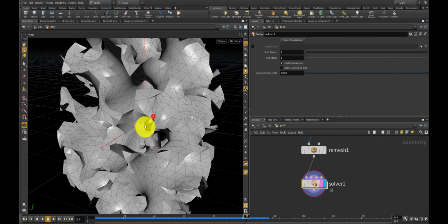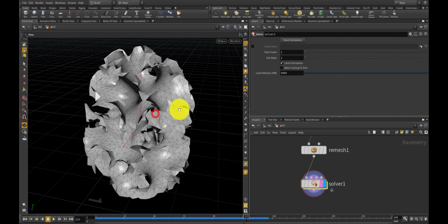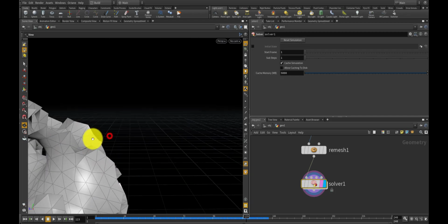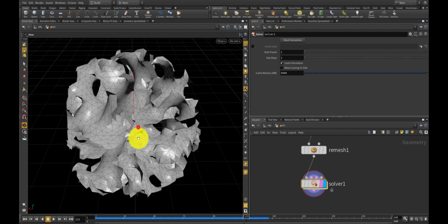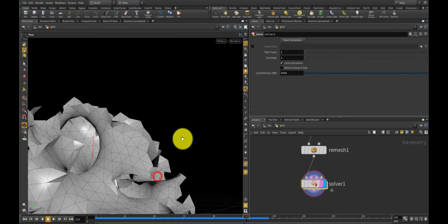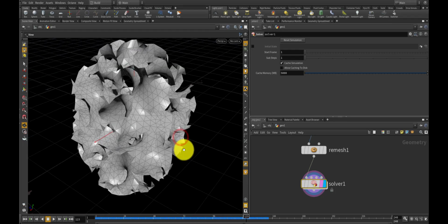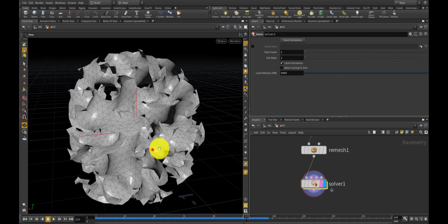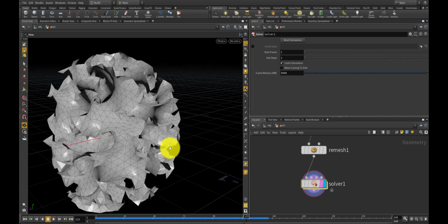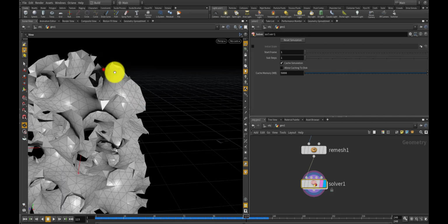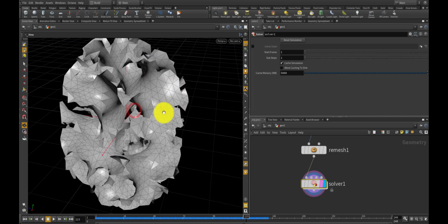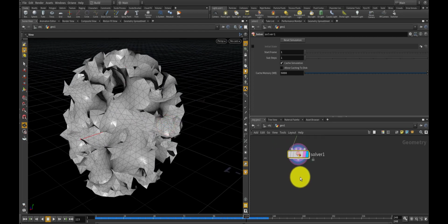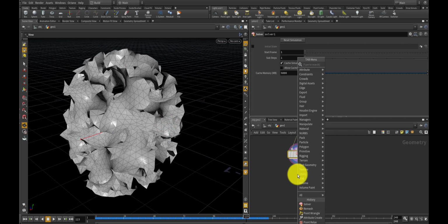First, as you can see, the edge of this mesh is a bit pointy, blocky. So I want to set the smooth for this mesh. And there is a smooth function in Houdini, but it doesn't seem to work very well for the naked edges of a mesh. So I'm going to apply some custom smooth function made in Point Wrangle.